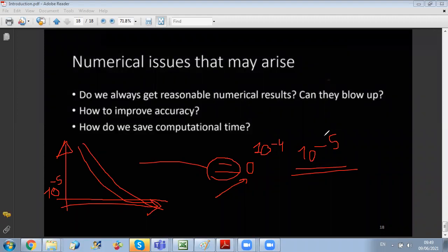And you don't have just one residual, because in a fluid problem you have to solve the energy equation, which will give you temperatures. You need to solve for the velocity field through momentum equations, etc. If you take a CFD course, you will also see that you have equations for turbulence in case your flow is not laminar. So it's a very wide field. You will look at your curves that should converge. This is what you want. You expect to have this result.